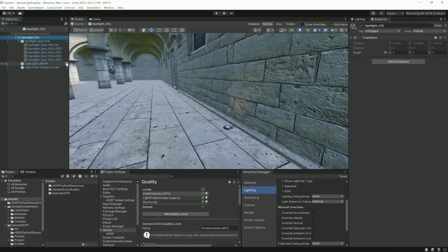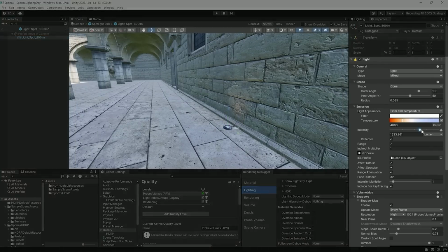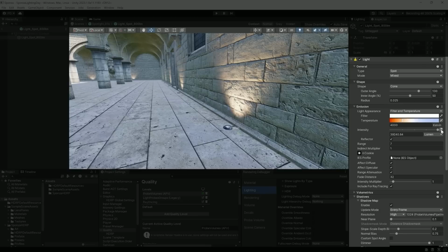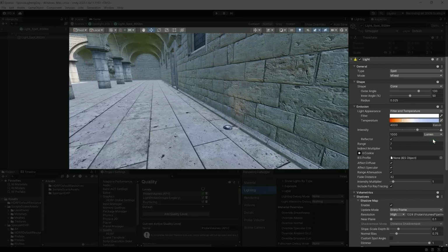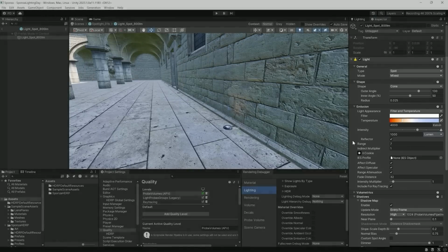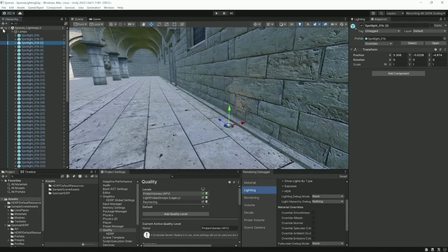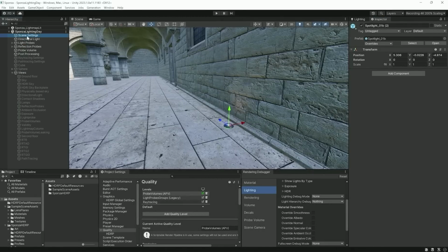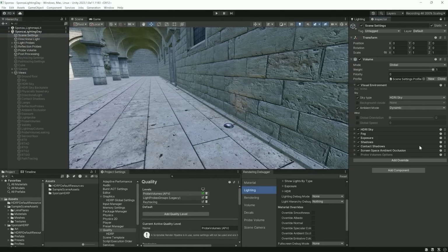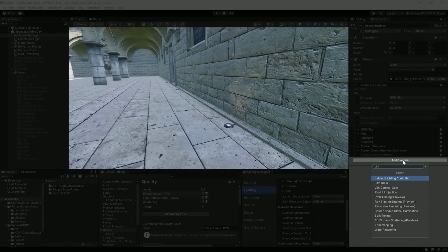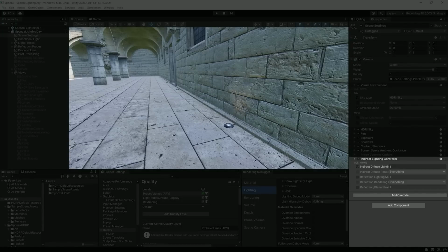Finally, let's have a look at the artificial lights. I can input an intensity in lumen manually, or use the interior preset at 1000 lumen. Units can be candelas, lux, or EVs. Our light doesn't shine very bright, however. This is because the ambient sky probe leaks all over the place and competes with the artificial lighting.